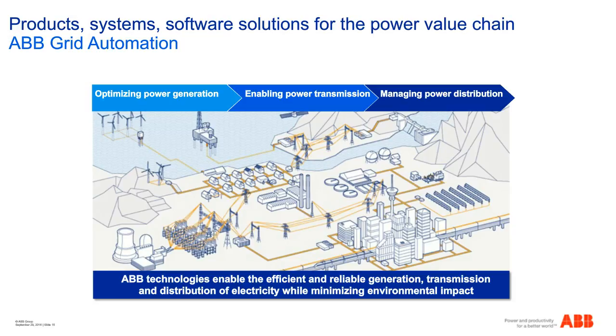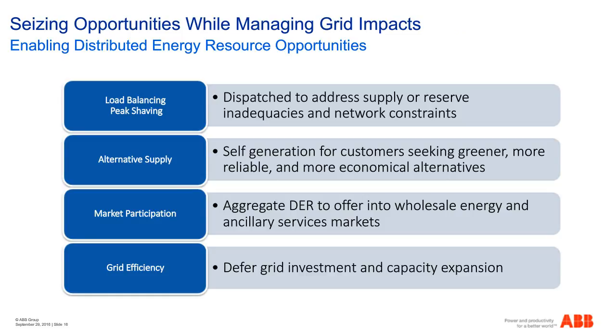If you've seen our white paper that we sponsored with Green Tech Media, Distributed Energy Resources, Seizing Opportunities While Managing Distribution Grid Impacts, we address a number of value propositions for DER. This list is certainly not exhaustive, but some of the ones that we include here are load balancing and peak shaving, which is the dispatch of DER to satisfy demand either locally or regionally or to shift peak demands.